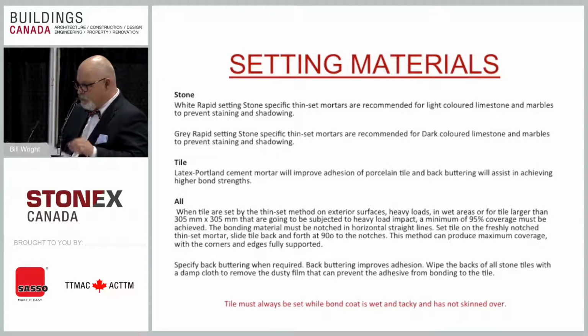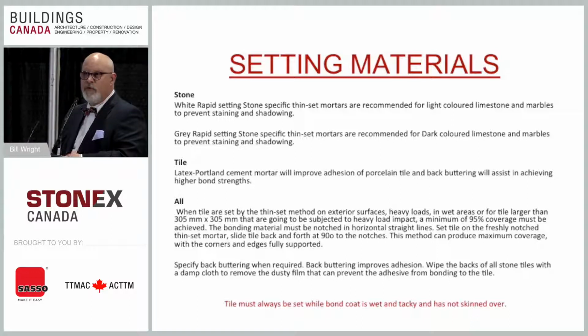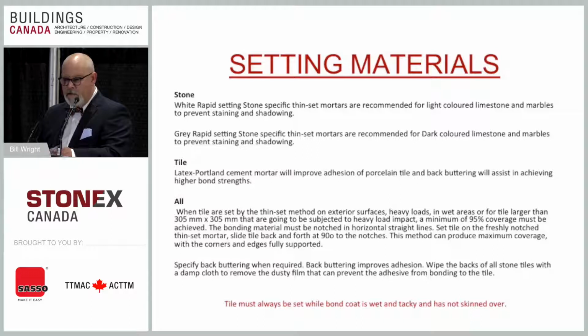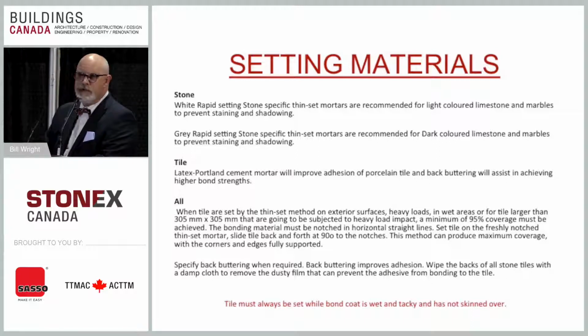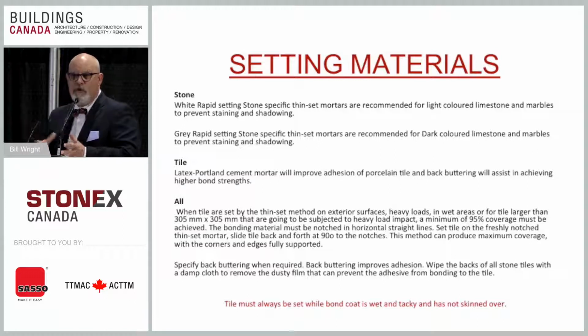Okay. Setting materials. We generally like rapid setting or white setting materials for stones. They tend to be light-colored limestones and marbles that can sometimes telegraph the darker mortars. There seems to be an idea out there that any mortar is good enough. I've got guys that, they all start off by saying they've been in the industry for 30 years, and they're using the same mortar for a tile that's a meter by a meter as a tile that they used for a 30 by 30 or a 12 by 12 15 years ago. Well, that product was never engineered to cure properly under a tile that big or to support that heavy a weight.